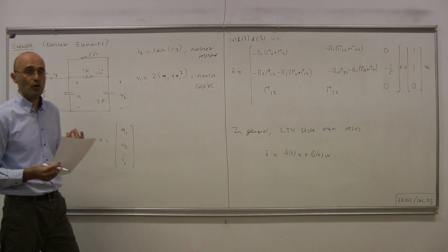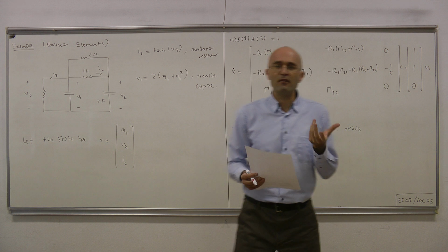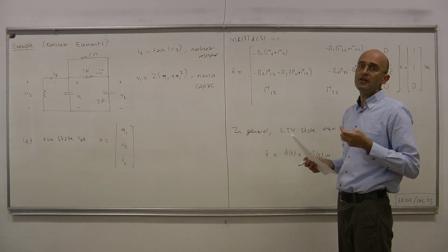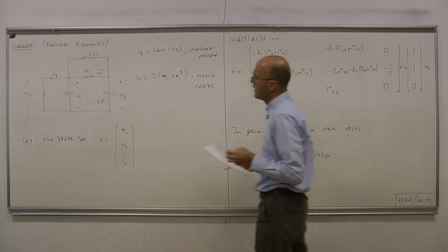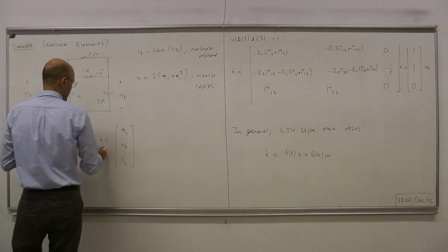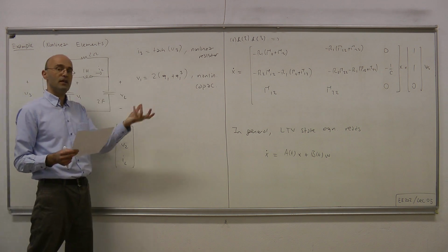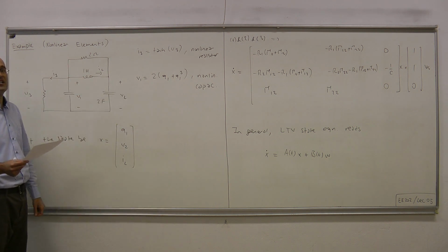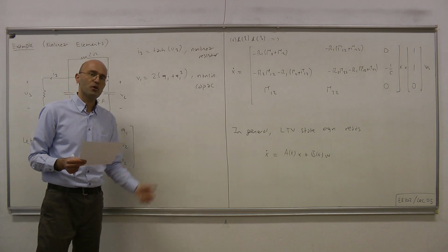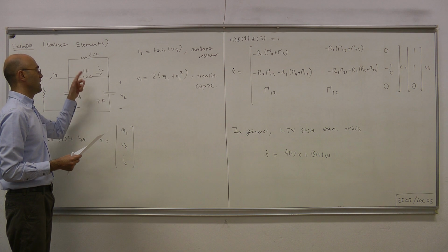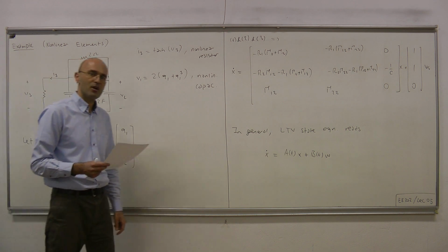For a resistive circuit, when you don't have an input, you don't have to really formulate or solve the circuit, everything is zero automatically. But for a dynamic system, even if you have no external inputs in the circuit, you will still have some non-zero response, due to initial stored energies or initial conditions of the dynamic components.